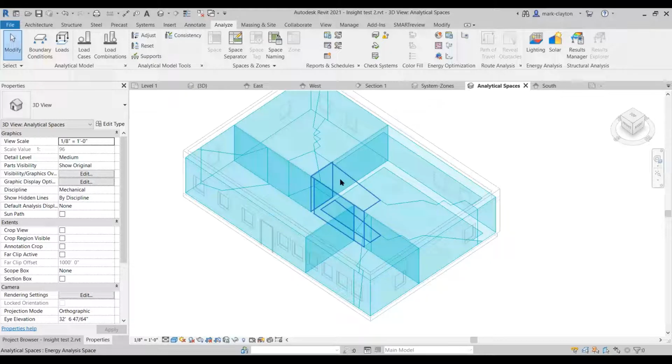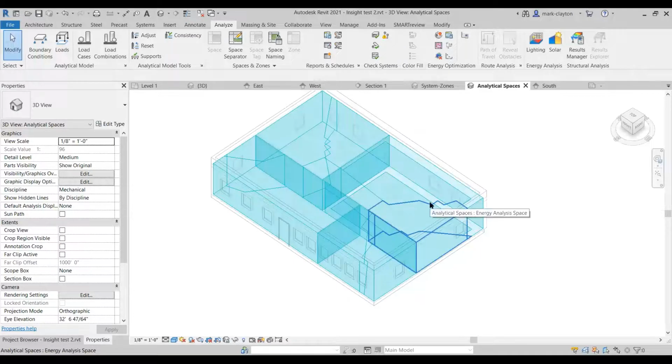Doesn't change very much depending on the weather conditions outside. Basically, windows are what affect your interior temperature. Yes, the opaque walls and roof affect it, but the windows are the major impact on the energy use. So, you don't have to worry about this. Revit did these calculations for you, and they will work just fine the way it did them.